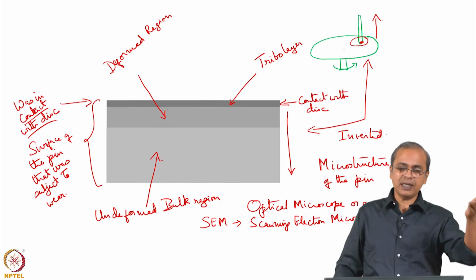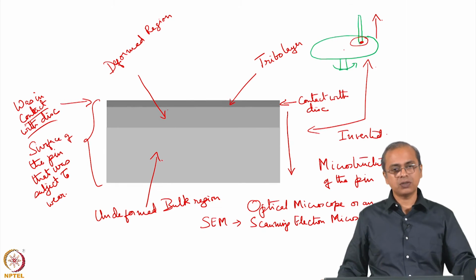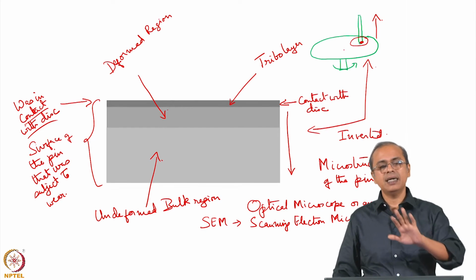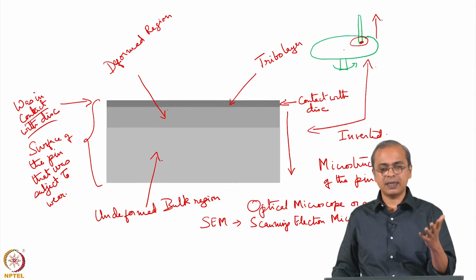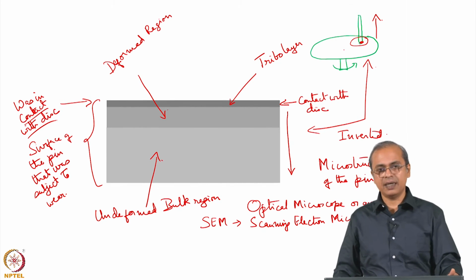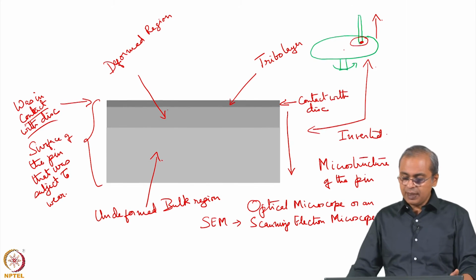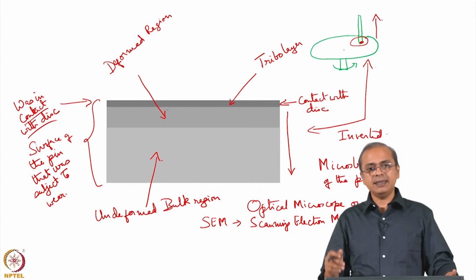So this process continues, and you eventually keep creating oxide, and then eventually you have oxidized all of that iron that is present there, and essentially you have damaged that sample. It is no longer that stainless steel that was there, it is a heavily oxidized sample. So the same thing happens when you do a wear test.